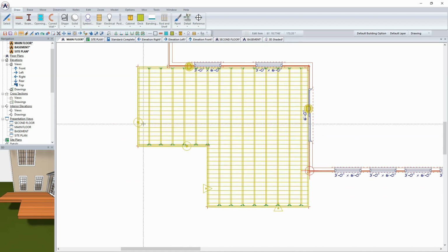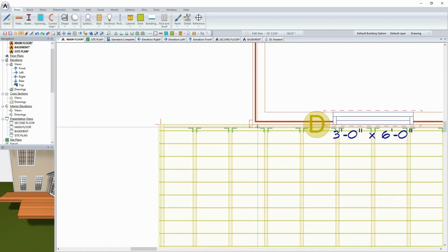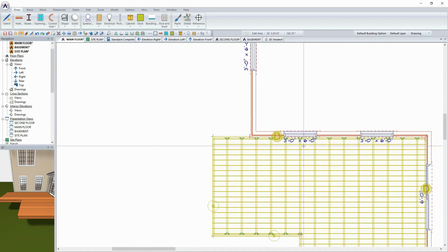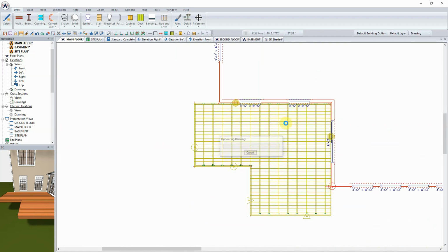So in the case where it's hollow, such as these two reference circles, it means there was no wall for it to snap to, so therefore the deck edge is left exactly where I traced it. Here, as long as I was within a tolerance of that wall, it snapped to it and automatically ran that along that edge for me.